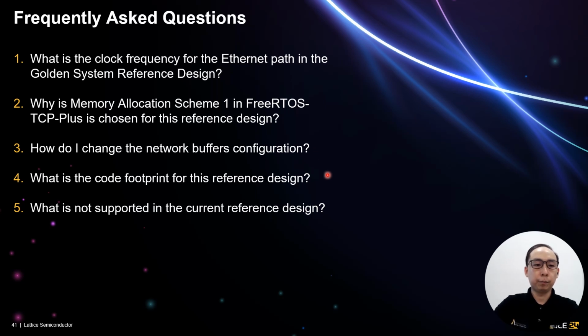Question number 4. What is the code footprint for this reference design? So including the FreeRTOS kernel, the network stack, and also network buffers, the code is now compiled at close to 400 kilobytes.